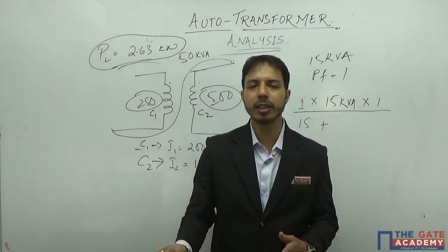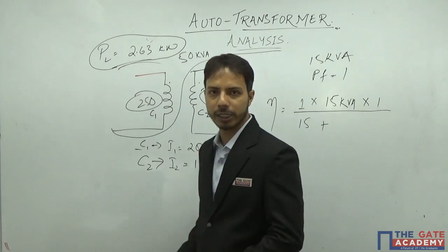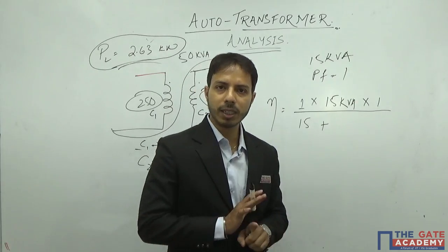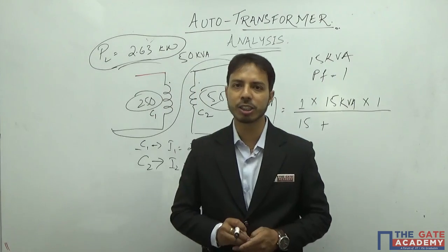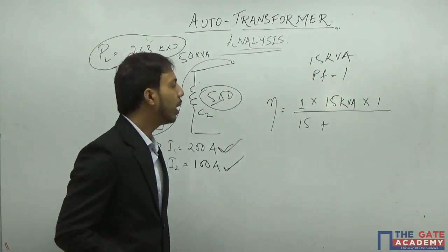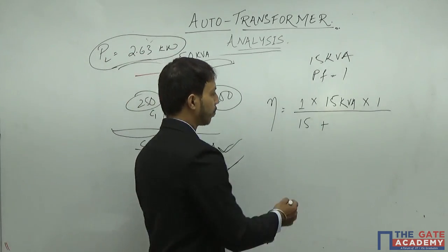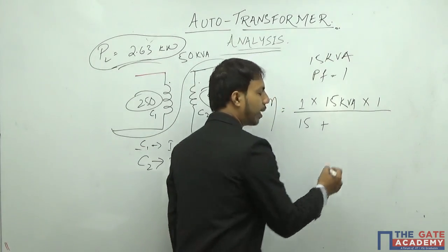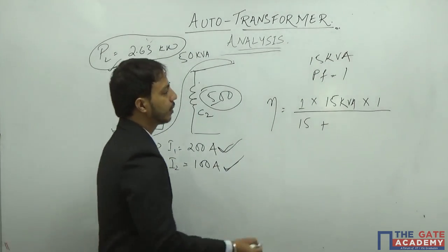After reconfiguring as an auto transformer, even though the output kVA is changing, the currents in the coils inside the auto transformer are not changing. That is the reason the copper loss will not change. Similarly, the iron loss will also not change, since we are using the same core. So iron loss and copper loss will be the same, which we have already calculated, which is 2.63.